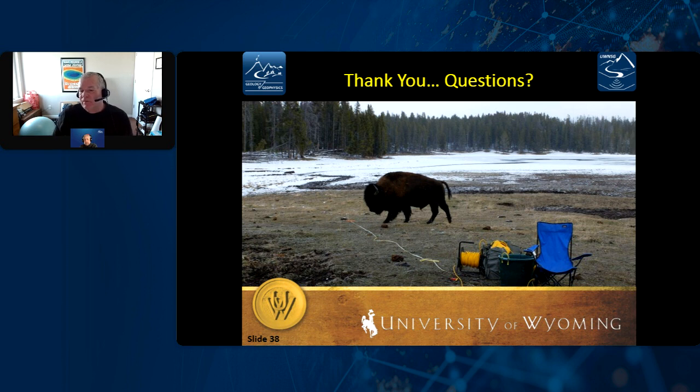If we were looking at a true near surface reflection survey, I probably would have been biasing a little bit more towards a meter for our station spacing. But at this point, we were a little bit exploratory. For all the lines, we basically had a 2 meter station spacing and shot spacing.